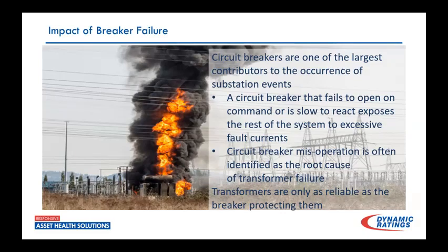So these breakers, that's really the reliability you have of your substation. Are these working as they should? And I know, especially the company Dynamic Ratings where I work now, we do a lot of transformer monitoring, and it is a very useful product for catching things early, in their inception, when you talk about transformer problems. But you also have to remember that that transformer is only as good as the breakers on either side of it. You're a breaker fail away from really doing some damage to that system.